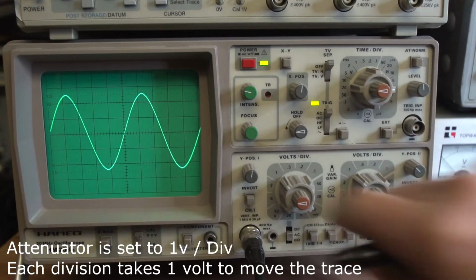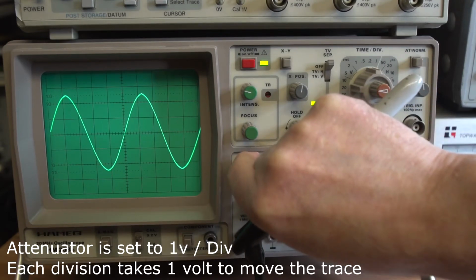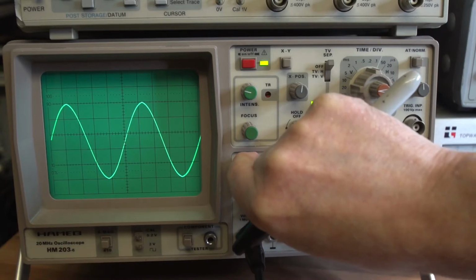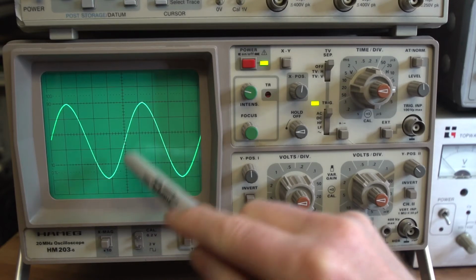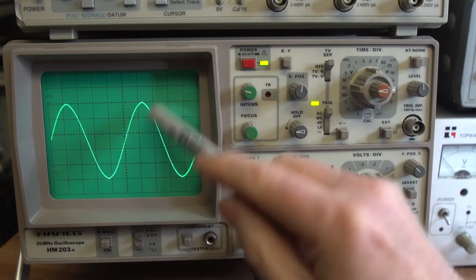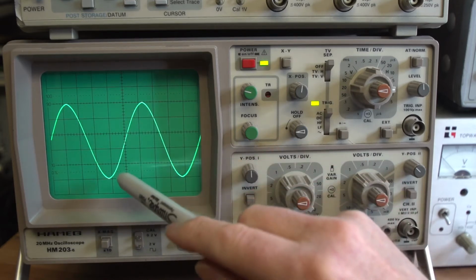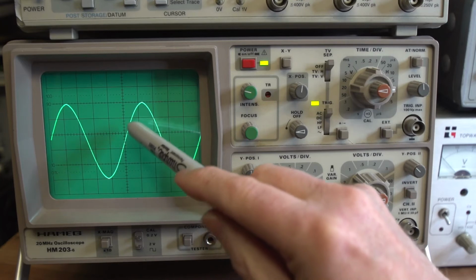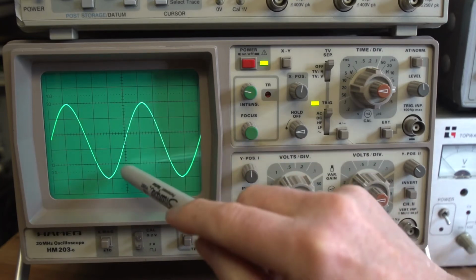And in this case you can adjust the position of the sine wave, just up and down. And I hope you can see it sits on this bottom line here, and it goes all the way up to this top line here. So if you count the graticule divisions between, it's 1, 2, 3, 4, 5. That's 5 centimeters or 5 graticule squares.